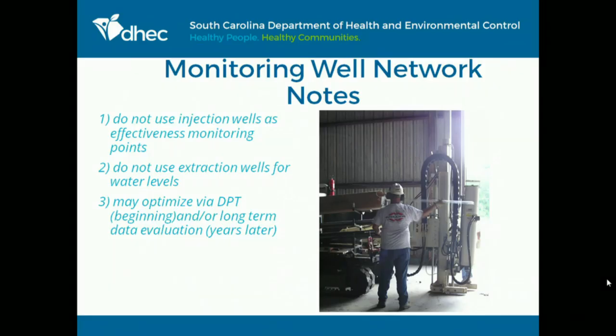Extraction wells are not appropriate for water levels because there's well losses within the well casing. And you'll find some people do water level maps with extraction well data points included. That's not appropriate. You can optimize monitoring well network using direct push technology. It's kind of hard to go back to the same point again and again. So long-term data evaluation is better if you can actually have permanent wells, but you can use direct push to supplement that.